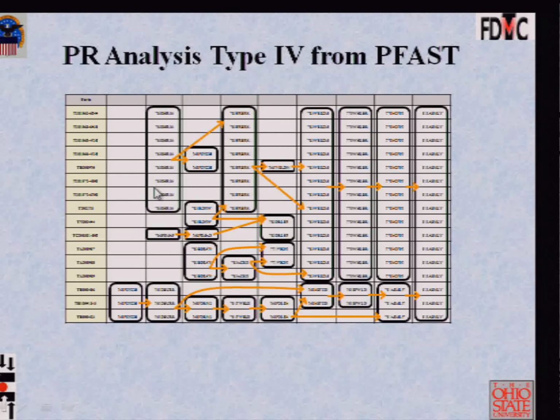Visual displays, Kanban squares, whatever have you. So once you know your part family, because all of them get produced on the same work center, you have an immediate guidance as to which parts should have their raw materials delivered to which work center. So these 3 components would have their raw materials delivered to the punch. All these components would have their raw materials delivered to the shear.